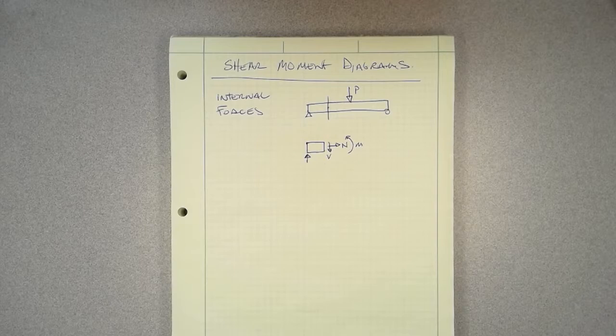We're also going to be looking at distributed loads. The distributed loads, this problem doesn't have, and we're going to cover that in a little bit. But where we have distributed loads that have an abrupt change, we need to make those a new section also. If it doesn't make sense, I wanted to lay that out there for you right now. If it's not super clear, I will do some examples in just a little bit.